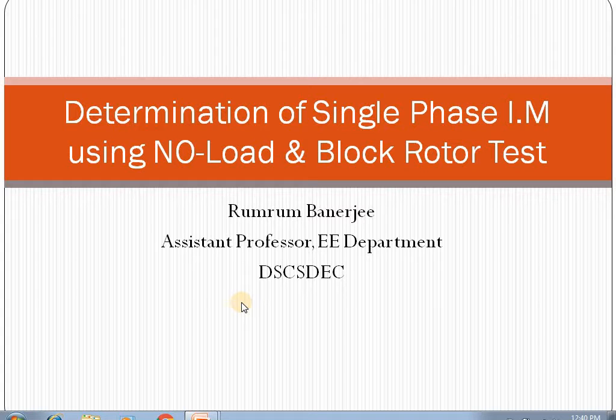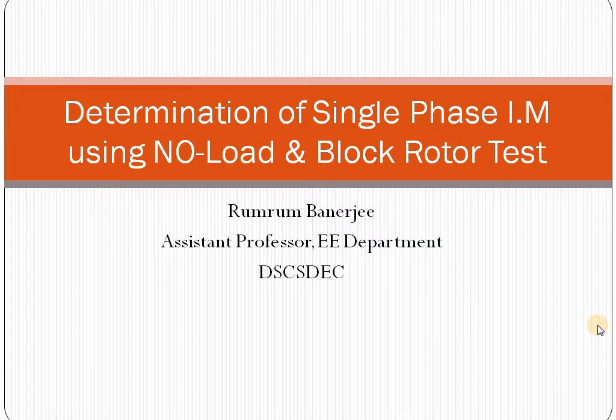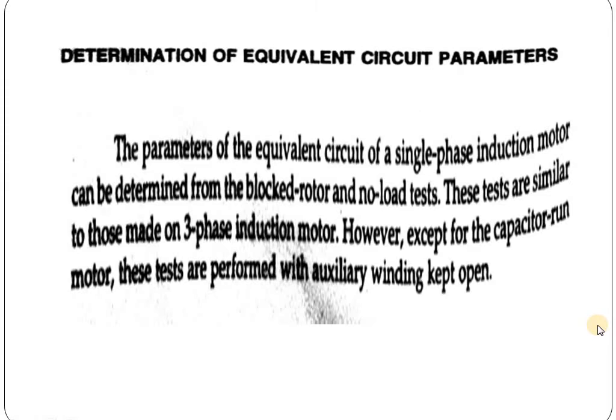First, it will be operated on no load condition, that means no loads will be connected with that motor, and second, we will block the rotor of the induction motor mechanically and then do the test. So let us start with how this test can be performed and how these parameters can be measured.